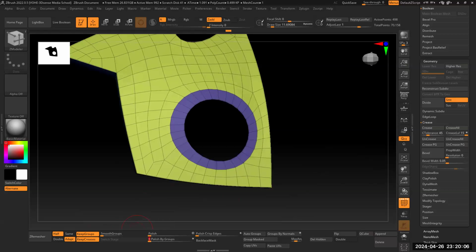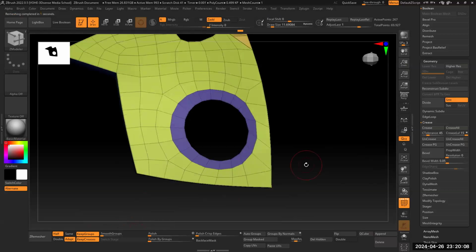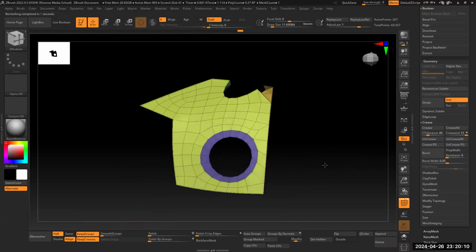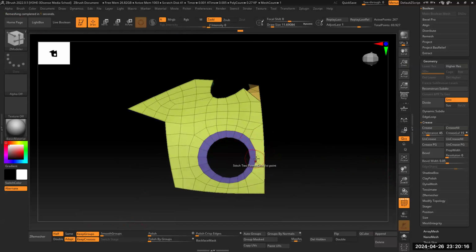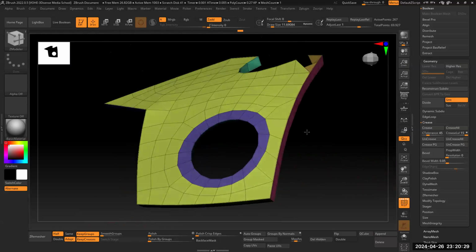Polish by groups, right? Yeah, you see? I get cleaner and cleaner results. Of course, this part I was ignoring, but the process is the same. Whatever funny shape, it helps, like in Maya where you have your edge loops. In ZBrush, you have your polygroup loops, right? And that gives you a lot of power because you're able to retain detail using the polygroups, right?